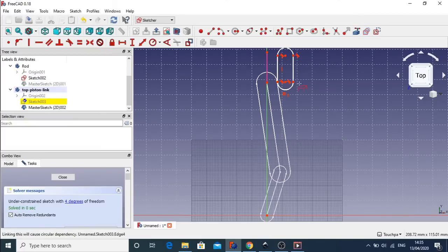There we go. So you can see you must hide these master sketches each time, these clones each time, otherwise you won't be able to import because they lay over the top of the actual one you've cloned. So again, constrain. Oops, let's pull this out a bit.